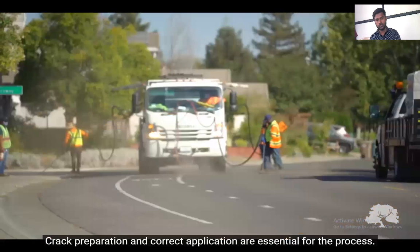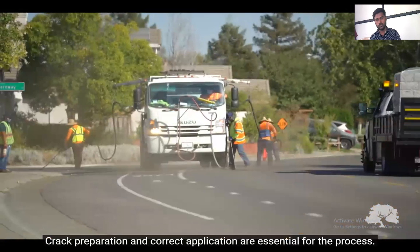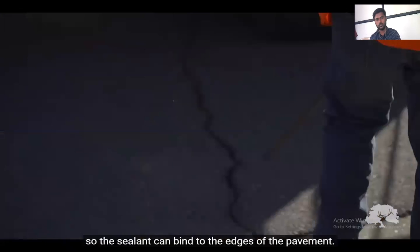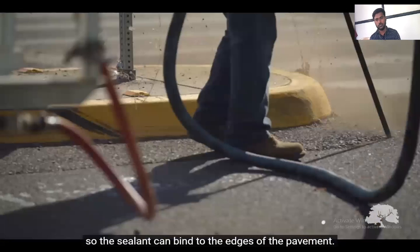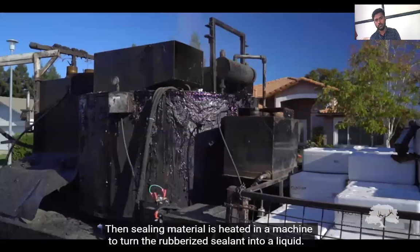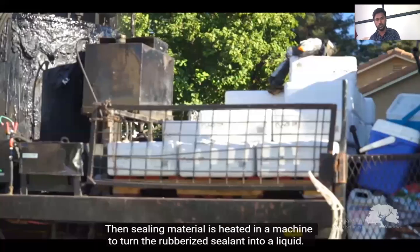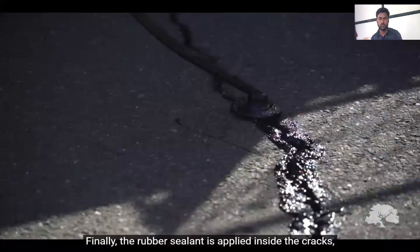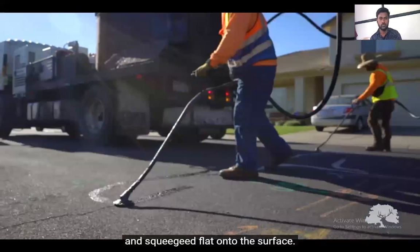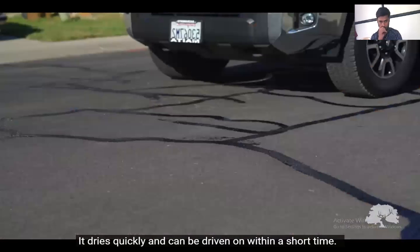Crack preparation and correct application are essential for the process. First, cracks and joints are cleaned of all debris so the sealant can bind to the edges of the pavement. Then the sealing material is heated in a machine to turn the rubberized sealant into a liquid. Finally, the rubber sealant is applied inside the cracks and squeegeed flat onto the surface. It dries quickly and can be driven on within a short time.